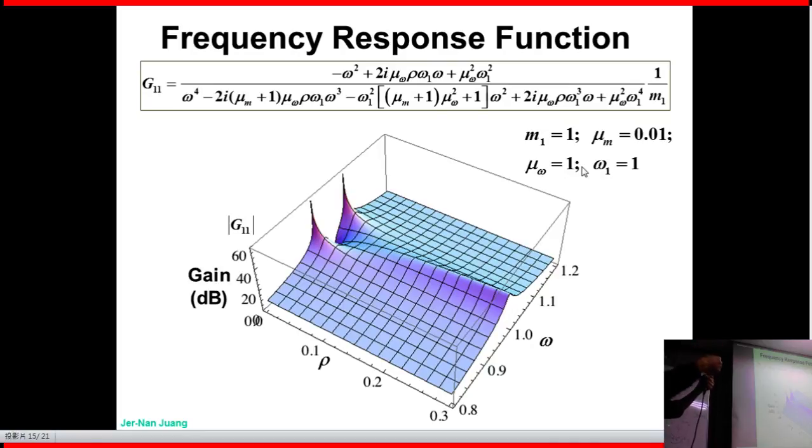So these two systems, TMD and building, have to have relative motion in order for my TMD to take the energy out of your system. Just like when we walk on a bridge, right? If you match your steps to oscillate with your bridge frequency, then the bridge's energy will transfer to yourself.